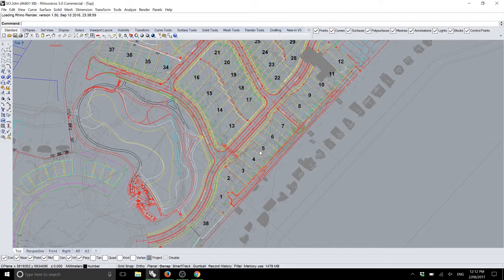Okay? So just to reiterate, a mesh is a cloud of points and instructions on how to connect them. So if this is point 0, 1, 2, then we would have instructions on how to connect them to make a polygon. So you're right, there are polygons. And usually in Rhino and Grasshopper, you are limited to 3 and 4-sided polygons. There are other meshes in the world that could have more, but we're limited to 3 or 4 sides. And so all that is a set of instructions, 2, 1, 3, 4, on how to join them, okay?